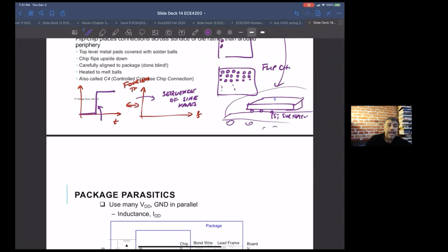So you'll see these fast edges a lot of times on your I/O, right? Like your microprocessor or FPGA is pumping out data really fast. So you'll have stuff at, let's say, 100 picosecond rise times. Okay, so there's a rule of thumb that I think you guys should remember. I just used it in a talk, that's why it's fresh in my mind.